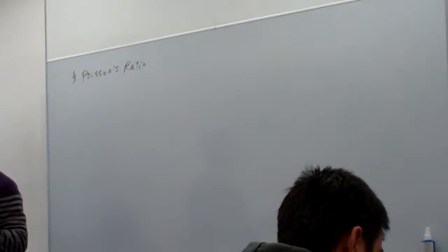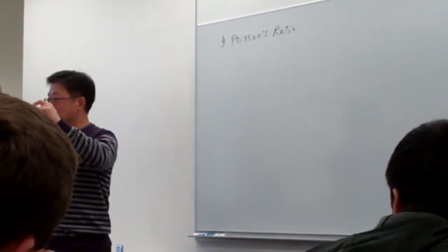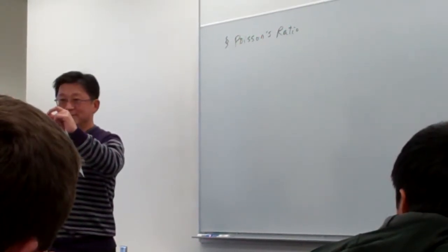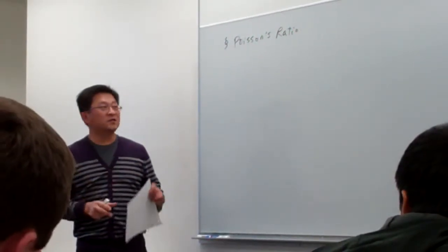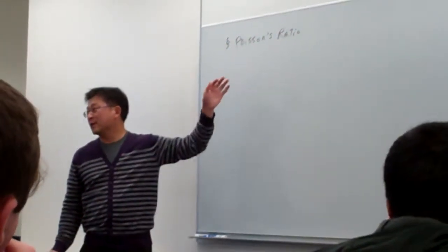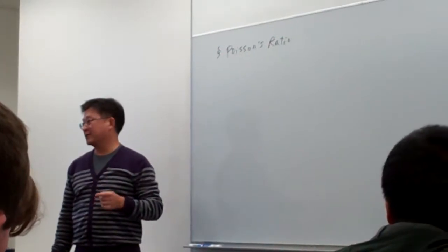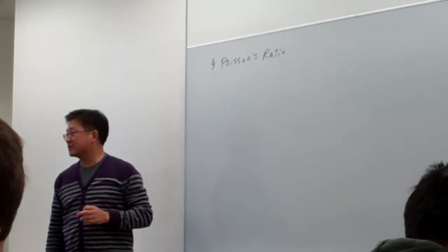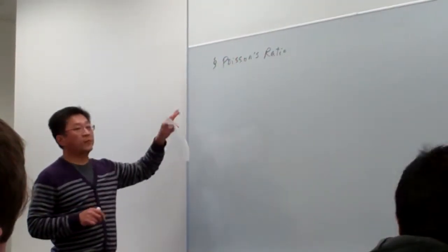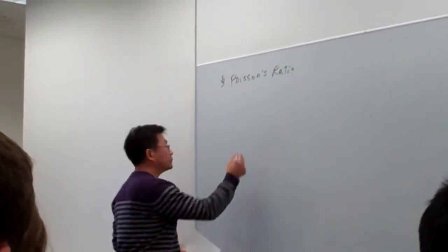For example, if you take a chewing gum out and stretch it, you can tell it's getting longer, but in the vertical direction, you can see it getting thinner, right? And that is taken care of by the Poisson ratio we're going to introduce. So from this point onward, whenever the problem statement mentions the Poisson ratio, that implies you must consider at least two-dimensional material models. This will make our model more practical and more precise. And what is Poisson ratio?